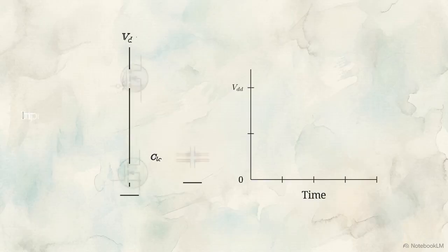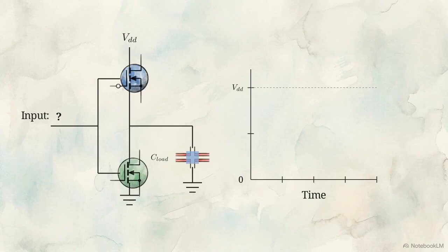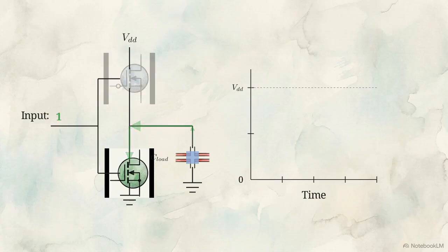A standard CMOS inverter uses a PMOS and NMOS transistor to drive an output node connected to a load capacitor. When the input goes high, the NMOS network turns on, providing a conductive path to pull stored charge out of the capacitor to ground. The NMOS is used for this discharge phase because its source is fixed to ground. This keeps the gate-to-source voltage high, allowing the transistor to drain the capacitor voltage entirely to 0.